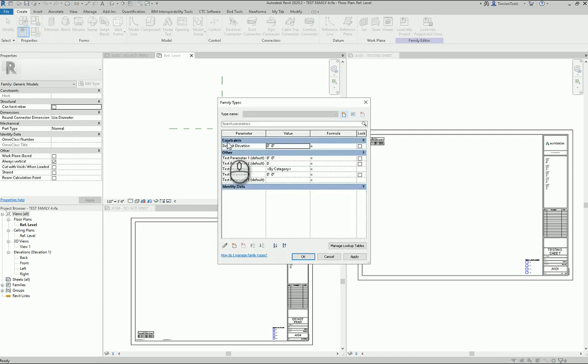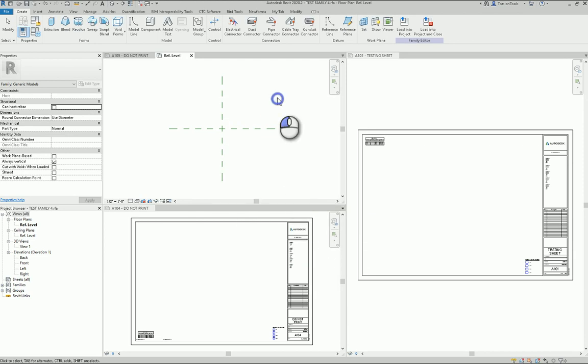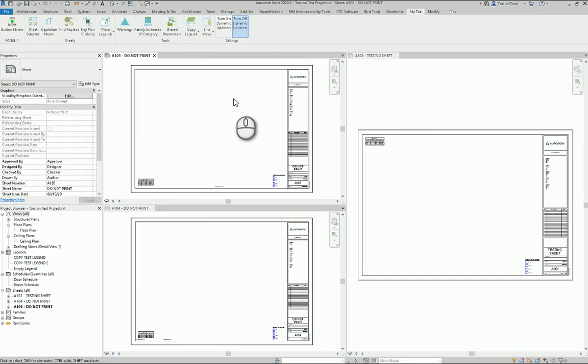But once we go back in here, you now see parameter 3 and 4, one's a material and one's a length, and they are type parameters. So that's just a really easy way, I feel like, to add shared parameters to multiple files inside of a directory. You can kind of just dump them in. Category doesn't really matter, as long as obviously they don't have any parameters with the same name already in them. It should take off and run. But those are the main updates this time around.